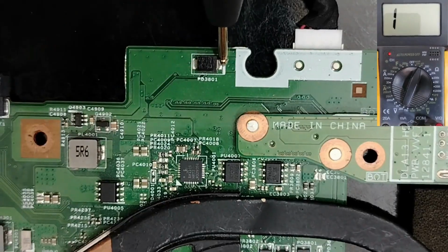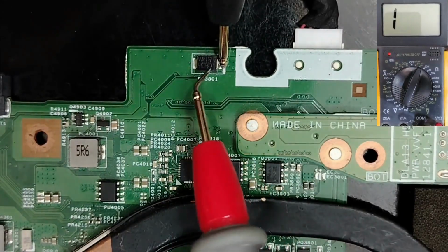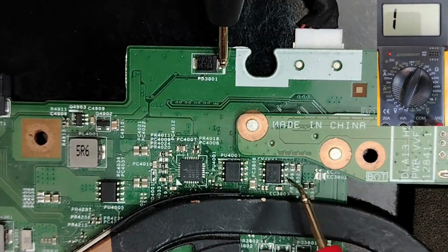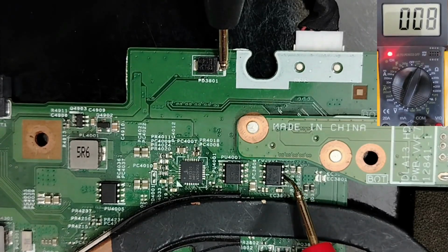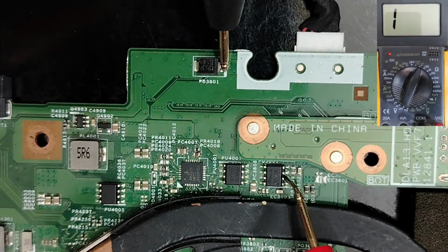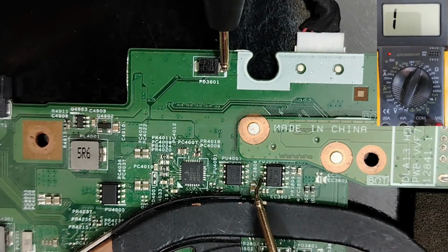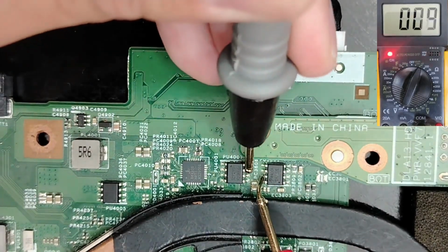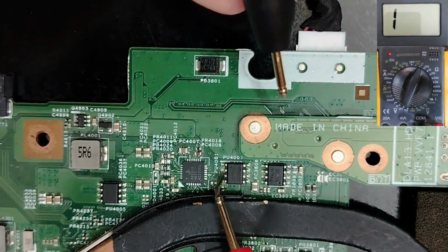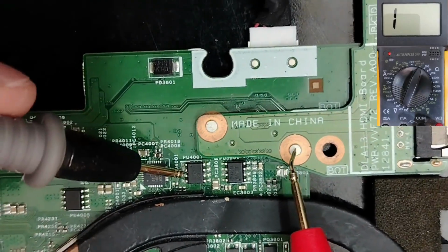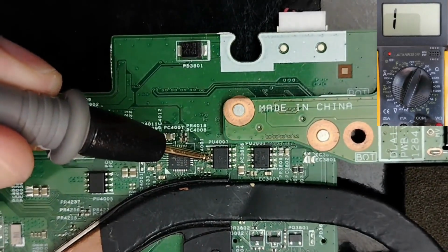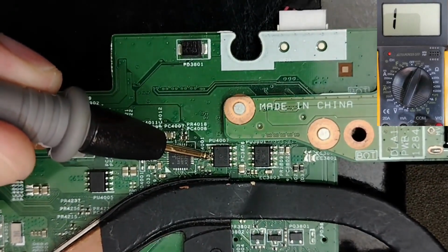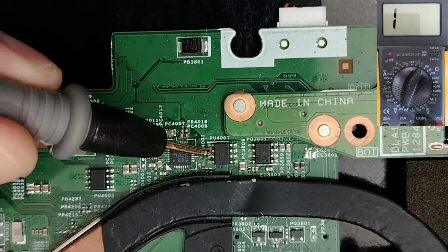After that I will put one probe here on the diode and go directly to this side of this MOSFET, to the source. Do you see? Continuity. And after that the power will pass from here, as you can see, to this side, and then will pass to this side here. So from this side, guys, if I put one probe here and go to the back to the current sense resistor, we will get continuity.